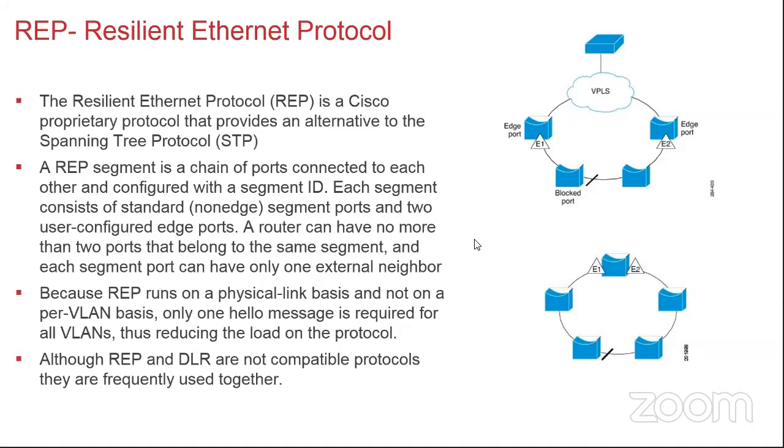So what we typically recommend, both Rockwell and TRC, if you provide us any documentation regarding your networks, is we're probably first going to be looking at a device level ring topology, which you'll see in a couple of slides. We can do it at the switch level as well, or potentially a redundant star topology similar to the EtherChannel, potentially even Flex Links, or the PRP design that David was talking about.